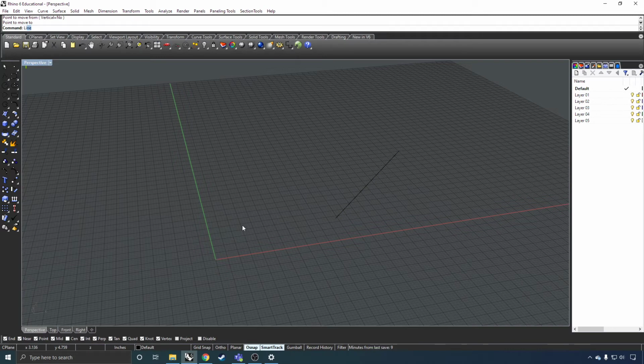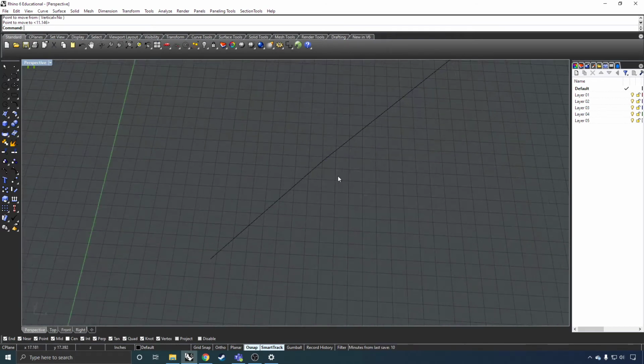So I'm going to make another line, just like that. And say I want to move this one so that this end touches that end. So from here to there, just type in move. So it's locked on, and you'll see it'll spit out different lines and stuff orthogonally. Now I'm going to go ahead and click on the end point there, and it told me it was on the end, and I'm going to put it on this end here. And so now those are connected at the ends. If I wanted to join those, I would start making what is called a polyline.